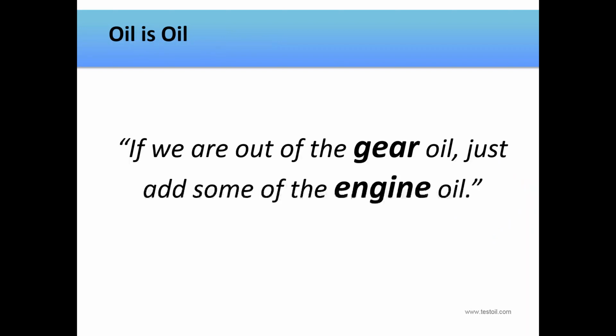So hopefully this gave you a basic idea of where we've come from and how we ended up where we are today. In the early 1900s, the thought, if we're out of the gear oil, just add some of the engine oil, may have been applicable. But in today's world, when there are about 10,000 different lubricants, and even more when you realize people mix them together, this thinking really can no longer be prevalent. The concept could even be dangerous today, resulting in shortened lubricant life or shortened machine life. And this is really a lot of the reason that I'm here today with you, to provide information on a way to determine compatibility between lubricating oils.